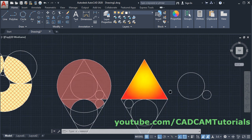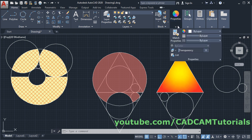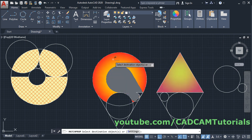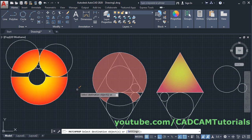And if you want to match two hatches, suppose here I want this hatch, then you can use match properties. Take your cursor to properties and click on match properties. Then select source object. I will select this hatch. Then for destination objects, I will select this hatch and press enter. So in this way you can match hatches using match properties.